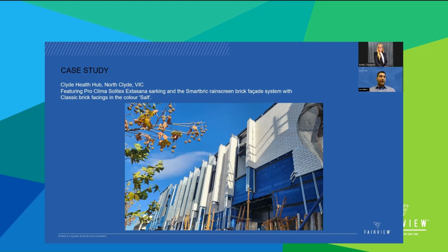So as part of a fire safety strategy, I would say that fire breaks are required at floor levels. And depending on the design intent and the layout, it is possible that vertical fire cavity barriers will be required as well. I hope it answers your question, Paul. You're welcome, Paul.